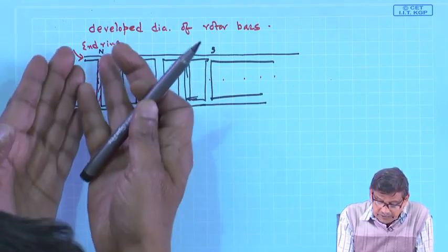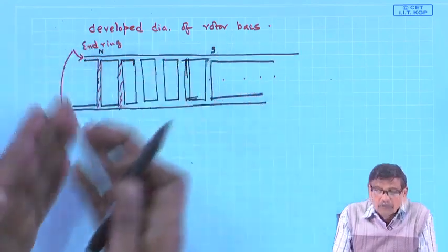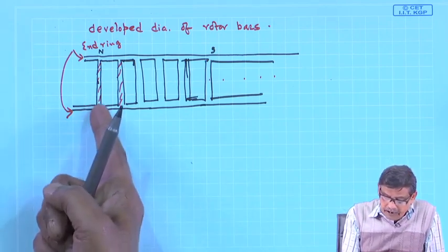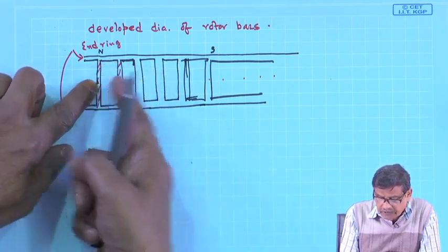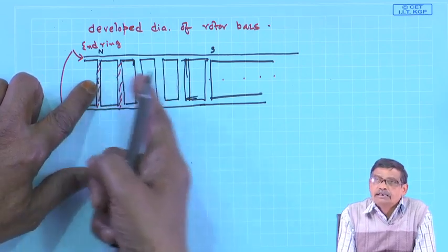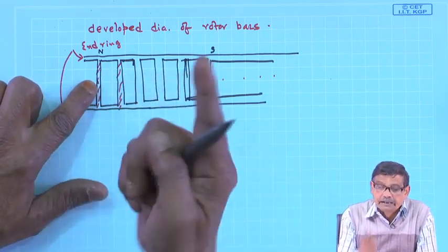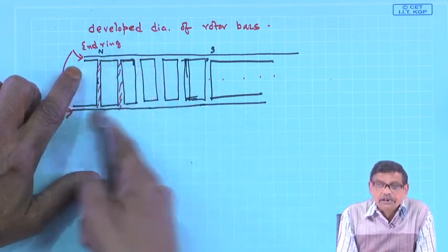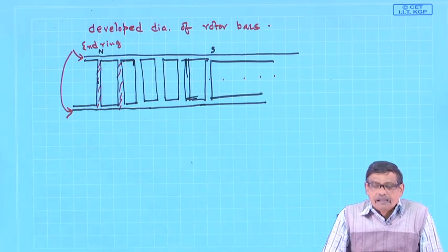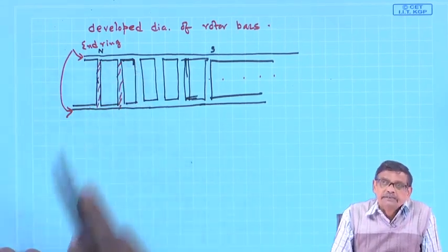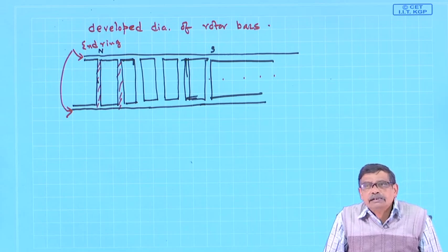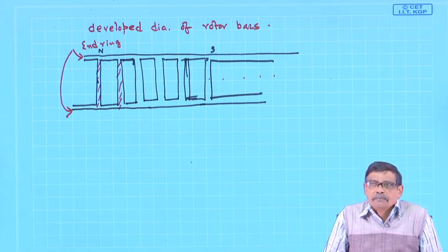No matter whether the stator is 4 pole or 2 pole or 6 pole, wherever a bar is there, you can find out after a distance of 180 degree electrical apart decided by the stator poles, a bar is present, and you can consider this to be a turn, and current will flow like this. Therefore, it will produce as many poles as produced by the stator coils.